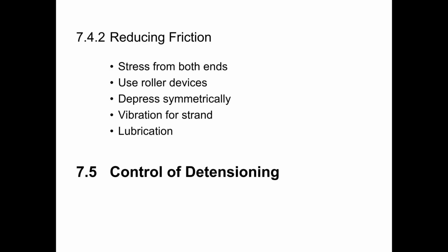All right, with regard to detensioning, detensioning is a little bit more complicated when we have draped strands. Usually we're going to detension a portion of the bottom strands and then the drape strands and then return to the bottom strands. In what proportion we do that needs to be dictated by the design engineer.